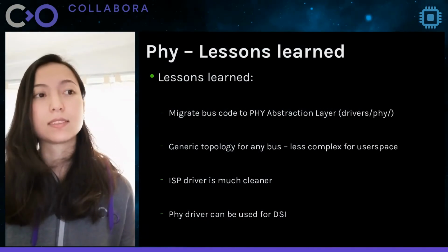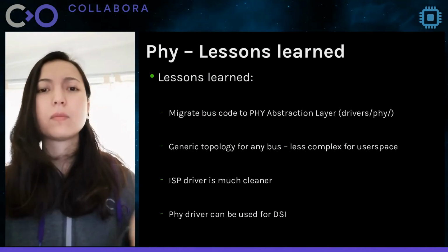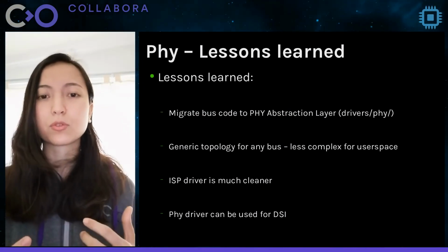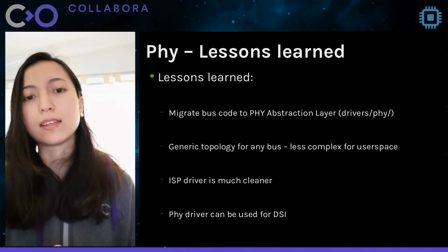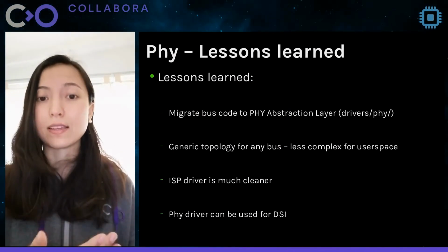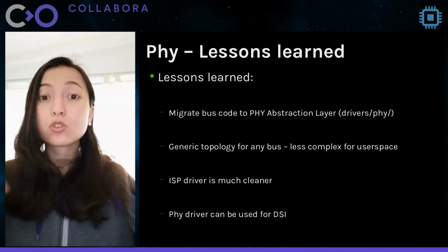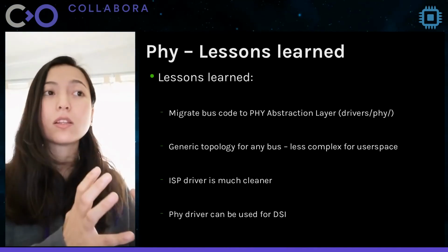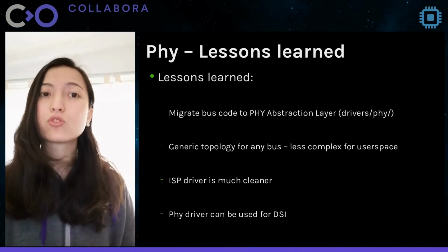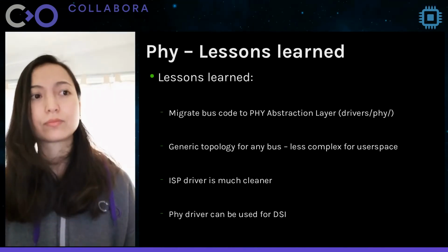Some lessons learned. If you have, so I see this and some other drivers that people post upstream, the code from the bus is usually integrated with the code of the ISP. So if you can separate those in 2 different drivers, one inside the media subsystem and the other one to the PHY abstraction layer subsystem under driver/PHY.